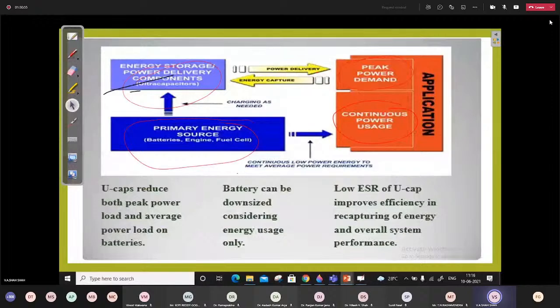Power demands, you can use this. Again, for these also you can have the two-way operation. And in this particular case, when we are using supercapacitor with battery, the peak power will be managed by the supercapacitor, and the size of the battery will greatly reduce. This again says that the overall weight and space requirement will further reduce, and we are able to utilize the full capacity of the battery. And that's why we are operating this device at its maximum efficiency.